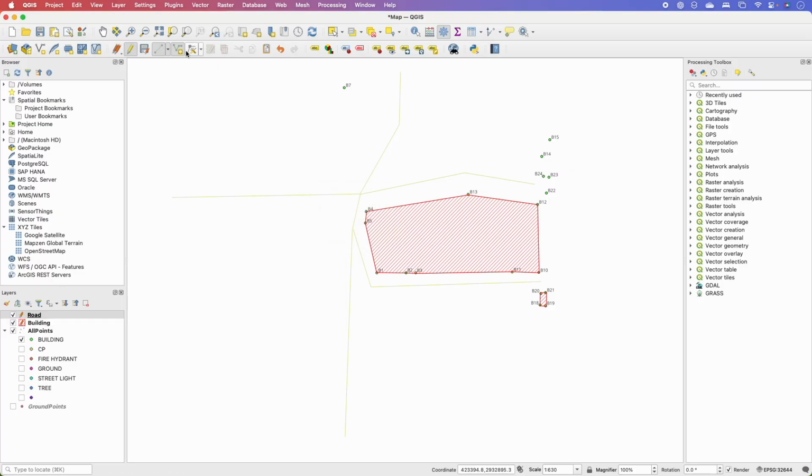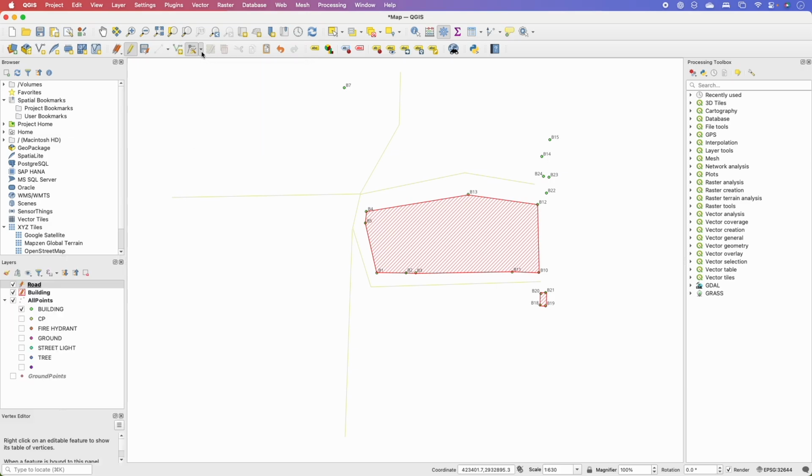Okay, and then there is this vertex tool that you can click, and then once you have drawn a particular feature, you can also edit it at any point of time. So you can just click on this, add a new node to it, or just replace existing node's position to fit in as per the points data. And you can go to another layer and then change the points location for that layer as well. So nothing is permanent unless you print the map. Okay, so you can go to any layer and then keep editing that layer in a way that is more